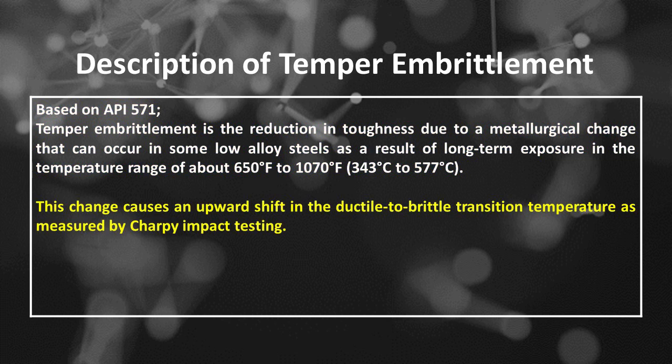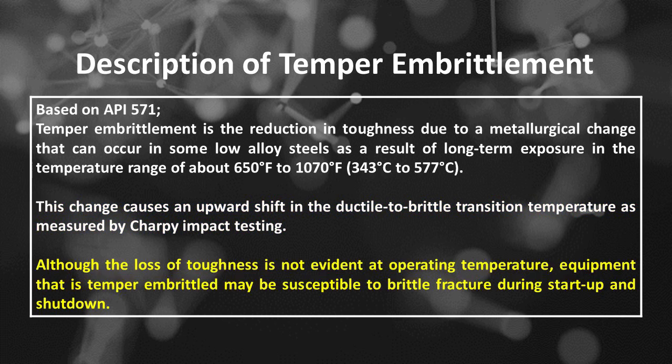This change causes an upward shift in the ductile to brittle transition temperature as measured by Charpy impact testing. Although the loss of toughness is not evident at operating temperature, equipment that is temper embrittled may be susceptible to brittle fracture during startup and shutdown.